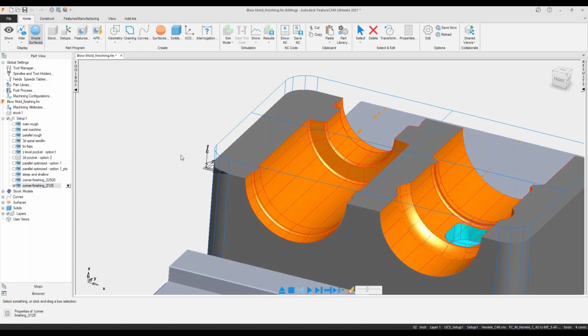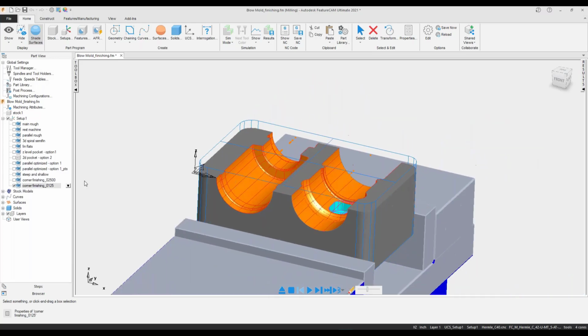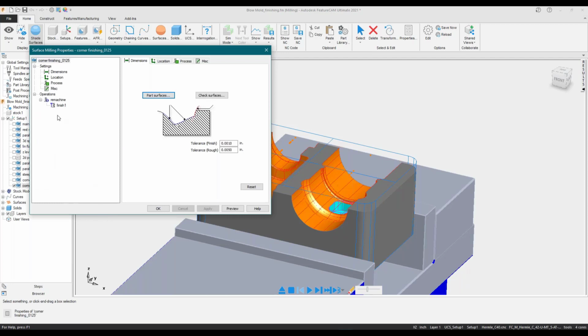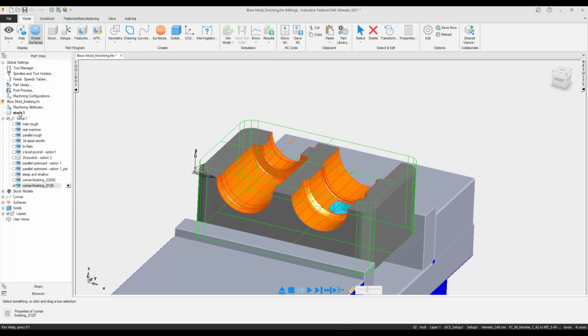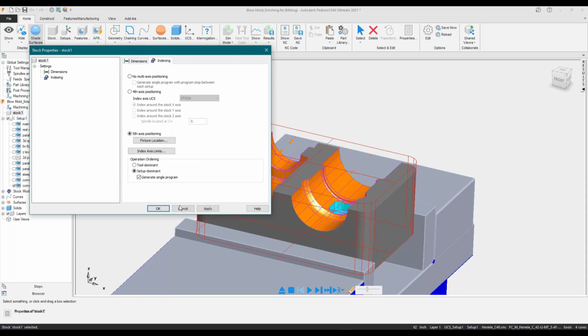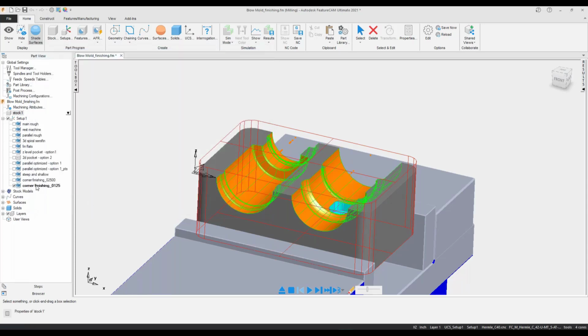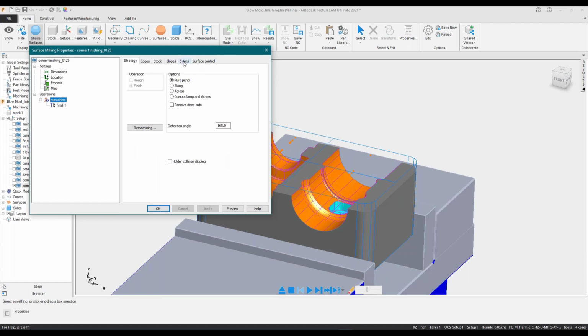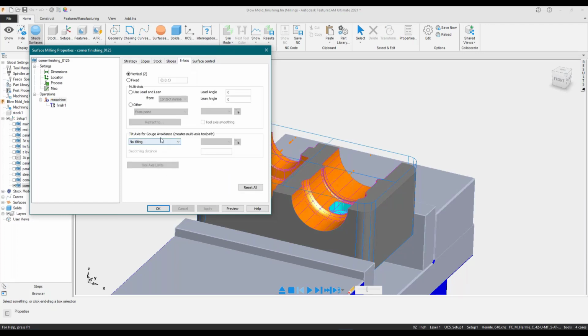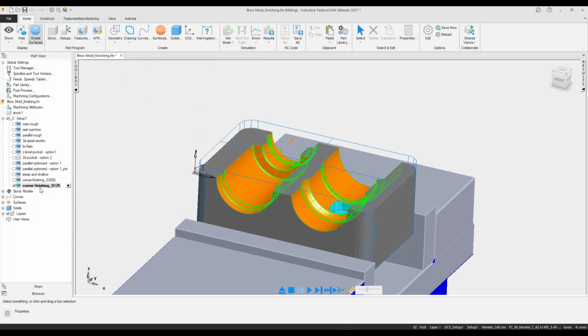This is where we can get into some of the 5-axis options in FeatureCAM. So if we were to jump into this strategy and the properties here, I'm going to jump into finish. Right now we have no 5-axis control because I just turned it off. But if we were to jump into 5-axis mode, let's turn this on and jump back into the strategy. So we now should have a 5-axis page. This is where we can turn on items like automatic gouge avoidance, or we can change the type of tool axis motion. So we've strictly used vertical or 3-axis since Monday. Let's go ahead and close this. And I'm not going to turn it on in this instance because it really adds to calculation time.